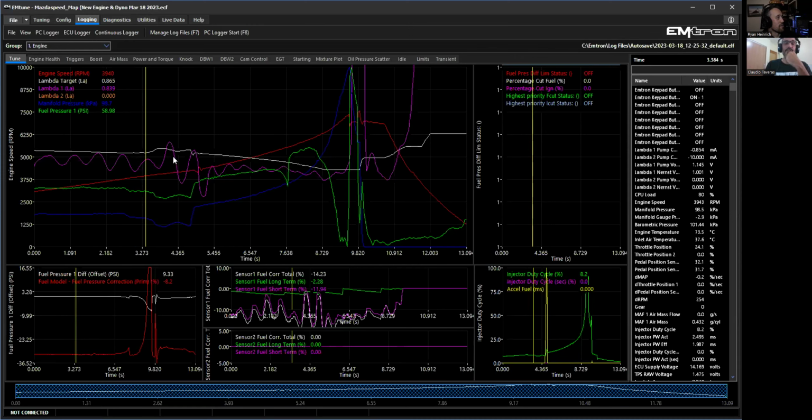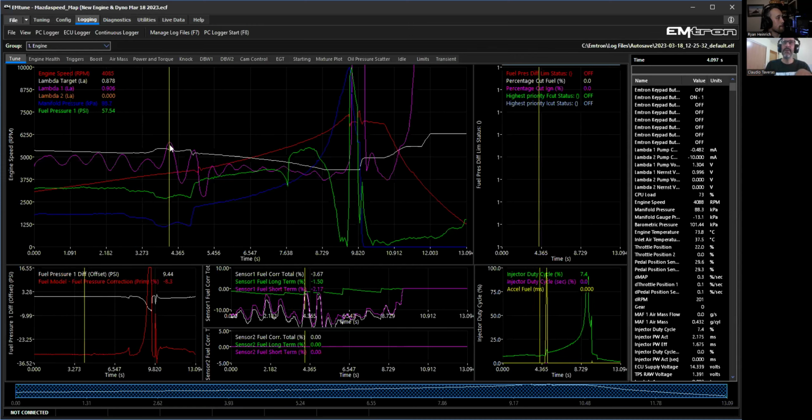This is probably over a year ago, well over a year ago. So this has gone through a little bit more polishing after this. The pumps were switched out. That eliminated the fuel pressure drop. The car eventually made 1,057 horsepower at 50 pounds of boost. That's amazing. On E85, on Ford ID 2600 injectors, and the car is a rocket.